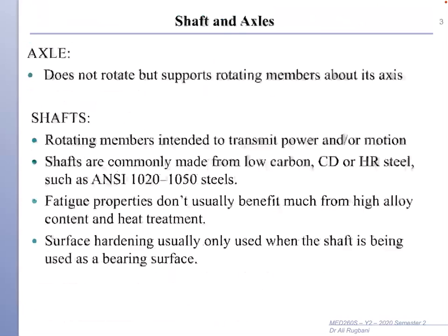Fatigue properties don't usually benefit from high alloy content and heat treatment in shafts. Also, you don't need any surface hardening for shafts unless you need a smooth surface.